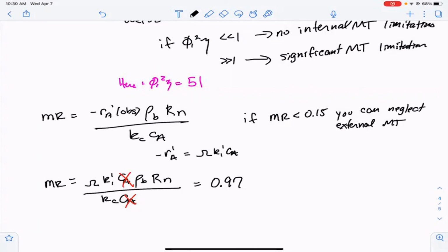your fundamental equations, knowing at the beginning whether you're internal and external mass transport limited or not. And if you knew some of these criteria, then you might even be able to get all the way back to dFA dW just equals K1 times Ca and not have to take any of the mass transport into consideration. But that's the framework that we've tried to develop over the last several lectures. And hopefully now this problem brings it all together.